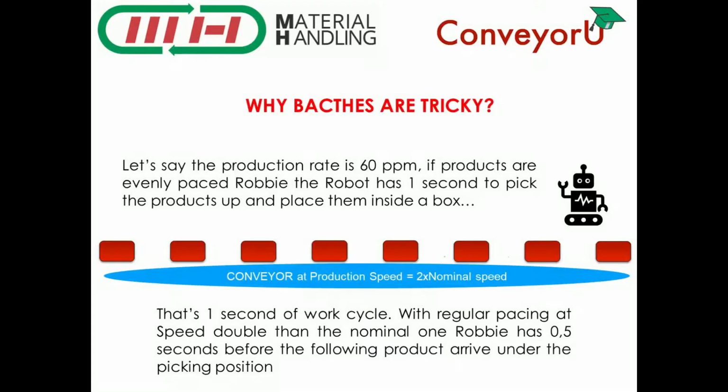So for example, let's say that we have a line that is running at 60 products per minute. Each second one product arrives, and we have a robot that can pick this product up, and it can do it without any problem if the products are regularly paced on the conveyor. Let's say that we are running at 2 times the nominal speed, so there is one product, one hole of the size of one product, and then another product, and so on and so forth. When the product arrives under the robot, it has 0.5 seconds to pick the product up, and then another 0.5 seconds to place the product on maybe a tray or something like that.